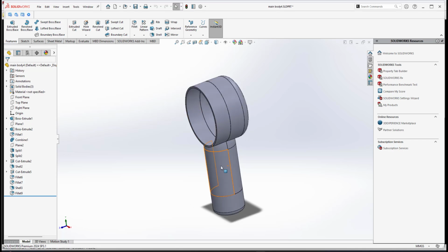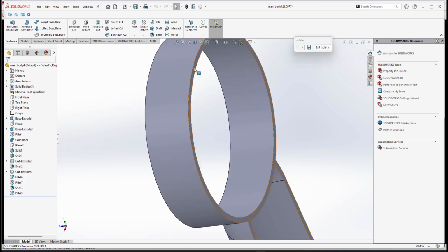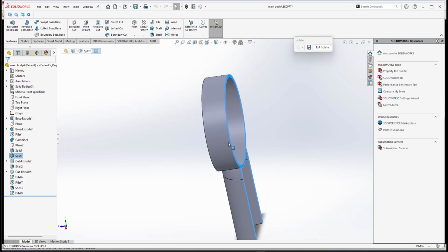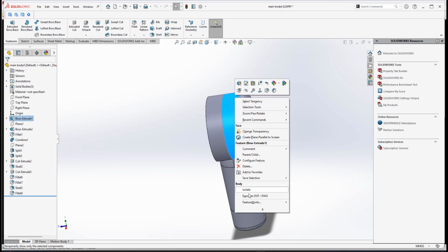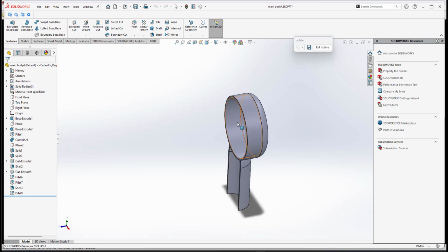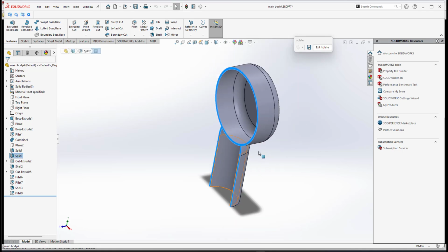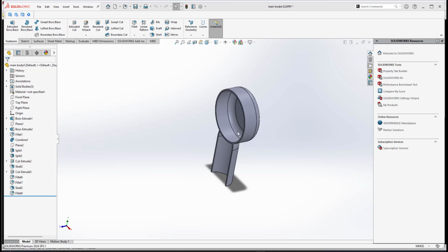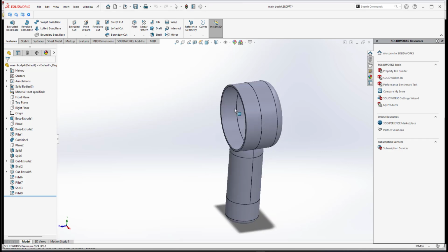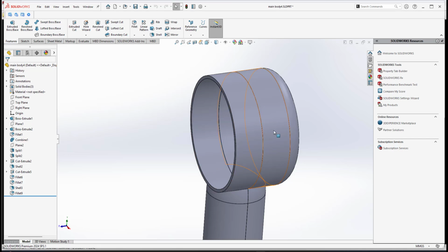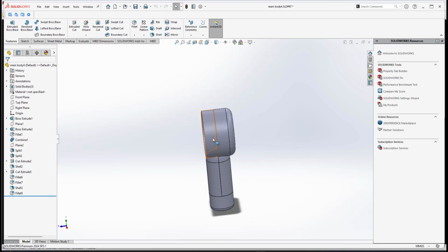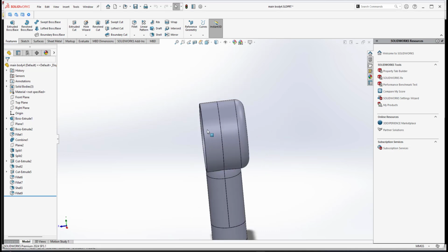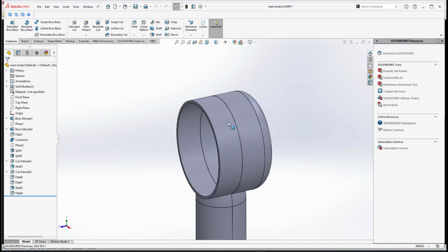If you look at the front part and the rear part here, this is the front part. If I select it, it's only jointed to the rear part by this flat plane. It's not supposed to be like that. This is the rear part. The rear part also is just attached by a flat plane like this. Actually, for plastic casing, it will not be like that. So we need to make fastening features. In SolidWorks, we have a fastening feature called lip and groove. So it means that this front part and this rear part will be jointed by fastening features, lip and groove.